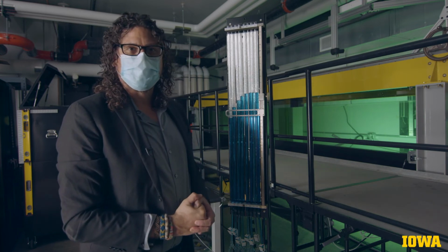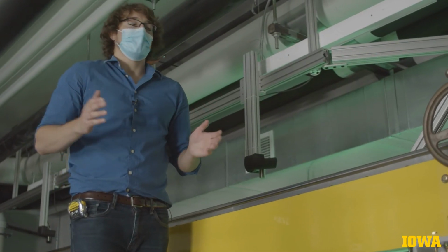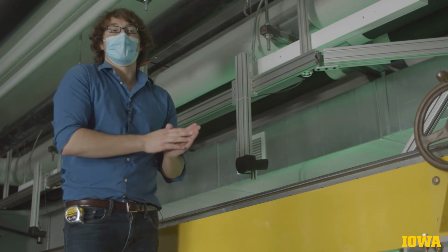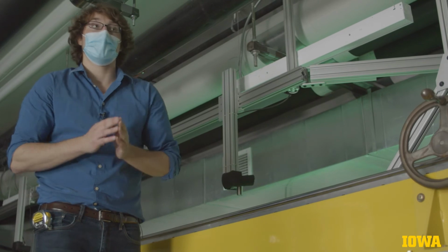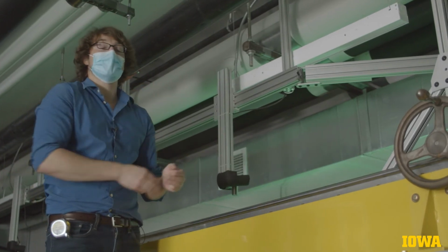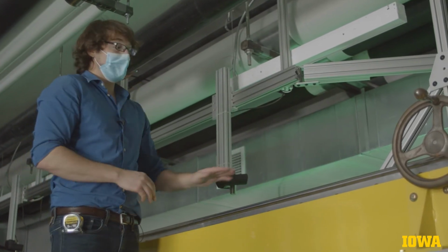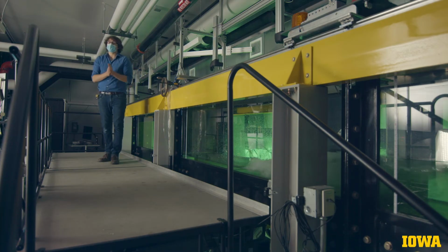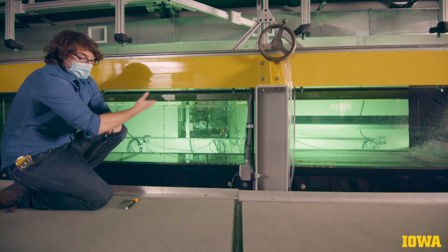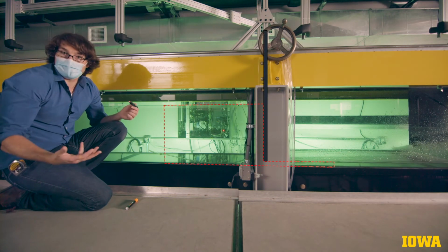reduction step. So besides the approach of measuring pressures and integrating them over the gate, we have at our disposal control volume analysis, which will allow us to calculate the force on the gate using only 3 measurements: the depth of the water upstream of the gate, the depth of the water downstream of the gate, and the width of the flume. So drawn onto the side of the flume here is our control volume that I showed